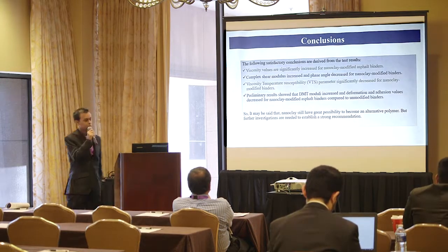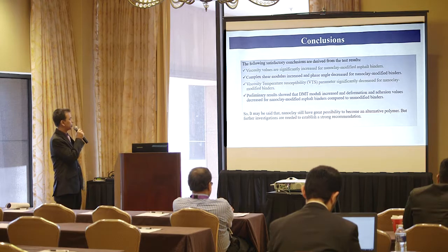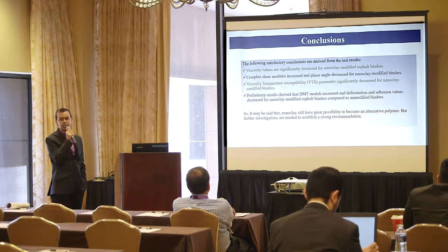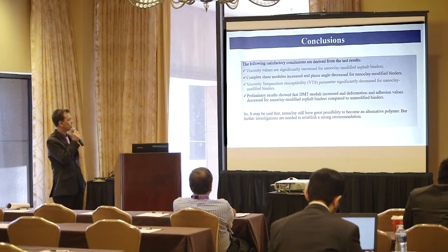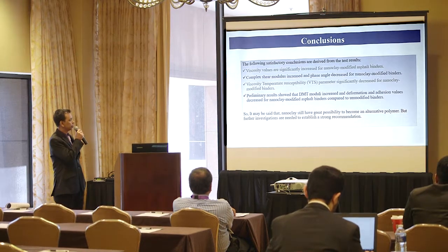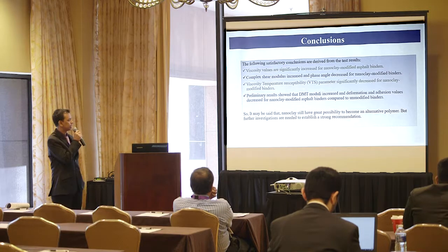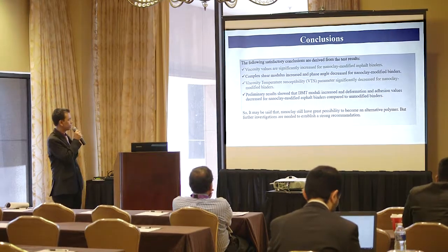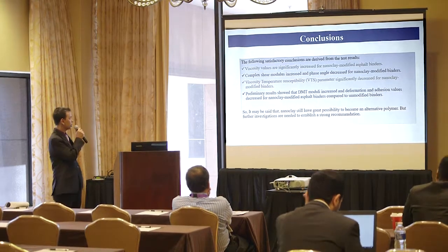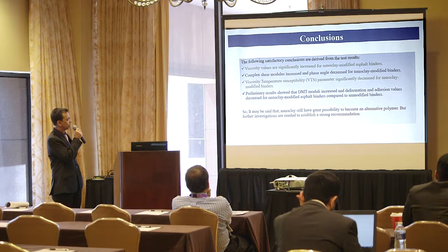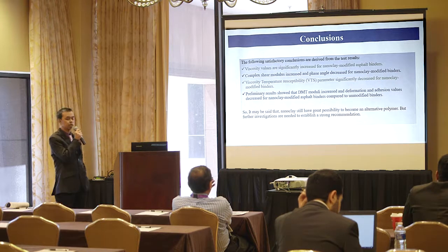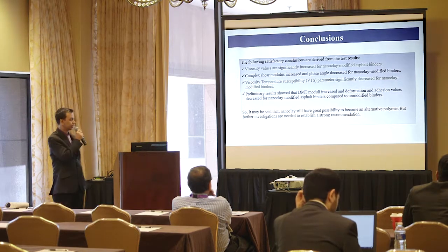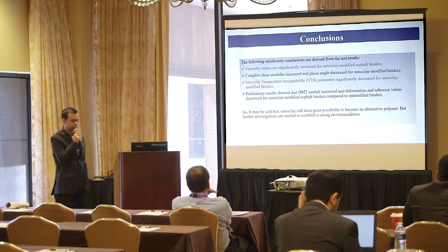After conducting these tests, we can say that viscosity values are significantly increased for nanoclay modified binders. Complex shear modulus is also increased, and phase angle is decreased. The viscosity temperature susceptibility parameter significantly decreased for nanoclay modified binders. And the DMT value is increased, and deformation and adhesion values are decreased. So it may be said that nanoclay has a great possibility to become an alternative polymer.